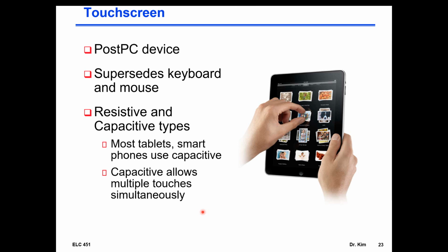However, you have to touch them with your bare hands. So for industrial applications where people have gloves and things like that, you have to use resistive types, which you don't have to touch with your bare hands. It doesn't rely on the electric field that you provide by touching it yourself. It actually relies on a different mechanism that is related to how hard you tap it.